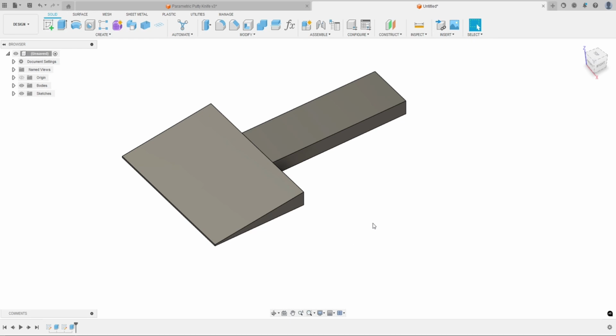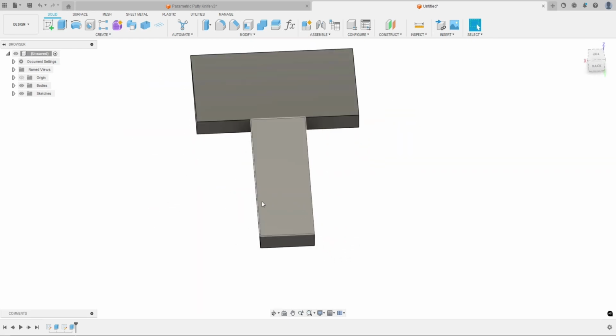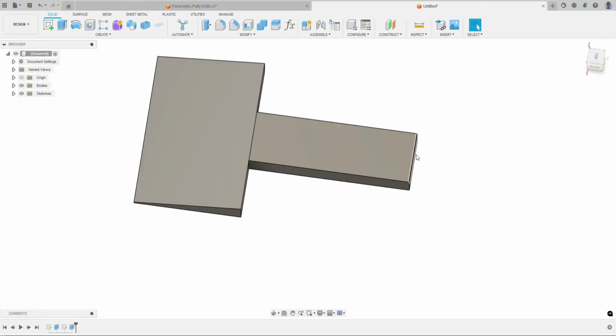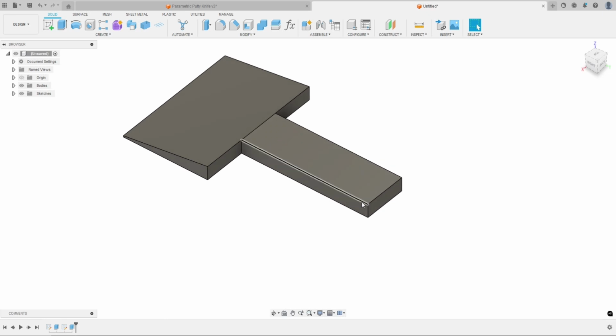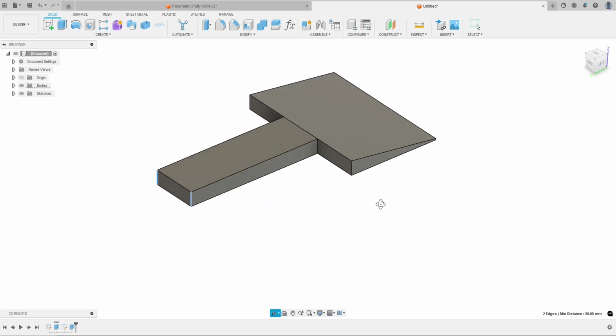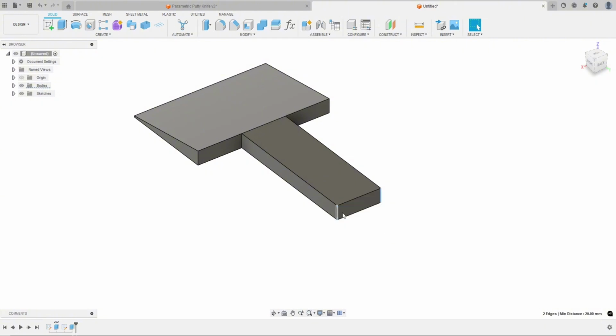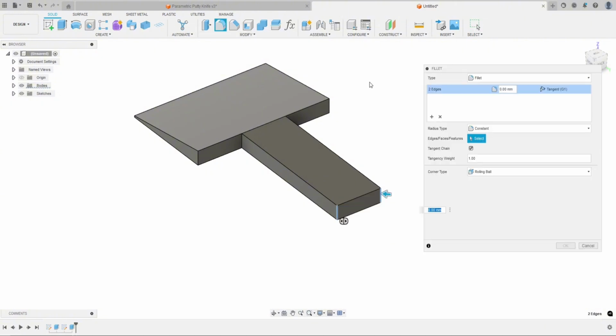We'll do two more things actually. So we know we want this corner to be rounded, or this handle to be a perfect half circle here. So let's create a bevel. So we're going to select a fillet, I guess, two of these corners, go to the fillet tool, and this is where we type in right here.